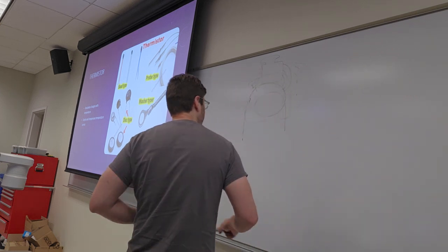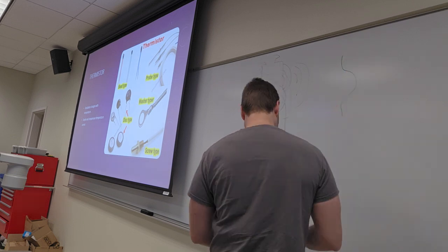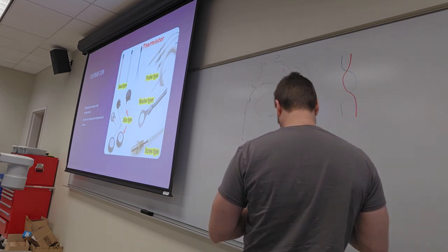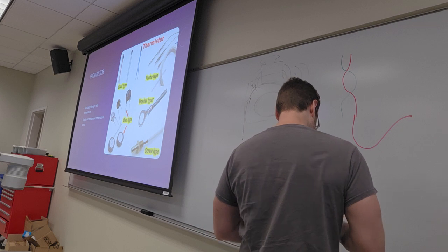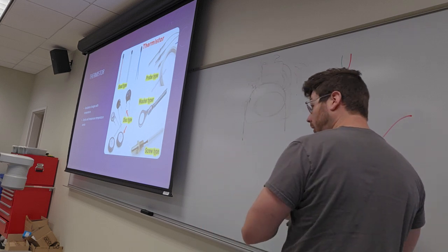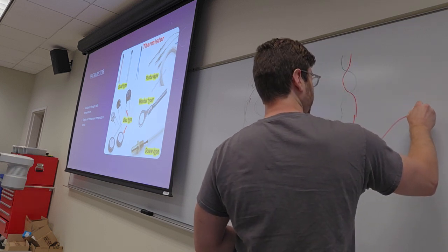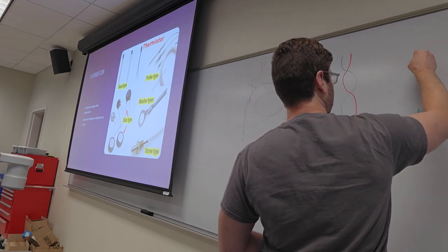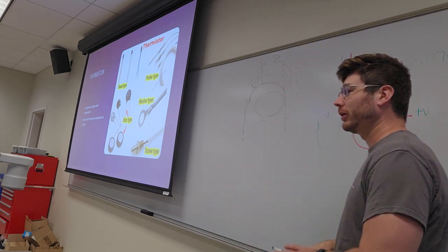Thermocouples work by using dissimilar metals that are wound together, just like this. Literally two wires. We terminate this one this way, we terminate this one this way, and if you measured these with a multimeter, just bare wires with a bare multimeter, you will find plus V, minus V. Between these two probes, I think it was like 0.7 microvolts or something like that, just as it is.